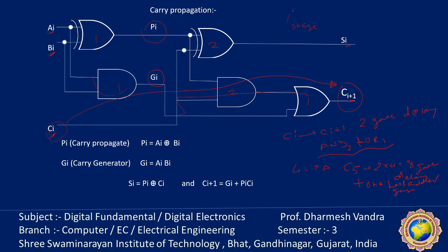The carry propagation time is the timing factor on the speed with which two numbers are added in parallel. Although the parallel adder or any combinational circuit will always have some value at the output terminal, the outputs will not be correct unless the signals are given enough time to propagate through the gates from input to the output side. Since all other arithmetic operations are implemented by successive addition, the time consumed during the addition process is very critical.